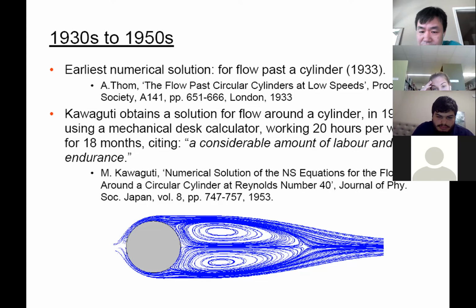When I see this result, although maybe not from a computer, still, the CFD result is not the calculation for a value. It's calculation of many values in the space. You have to divide this space into many small elements. On each element, you need to calculate the velocity. I mean velocity, not just speed. Velocity means the speed plus the direction. So on every location in the space, you calculate speed and the direction. Then put them together, you can create the field like this, vortex.